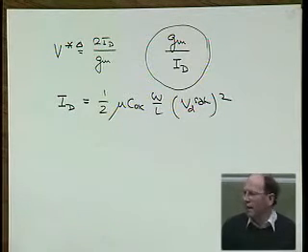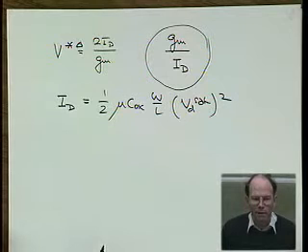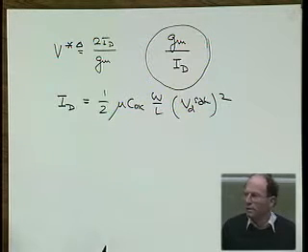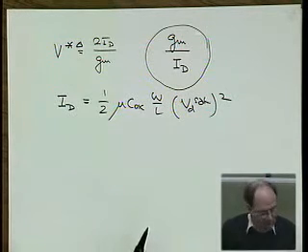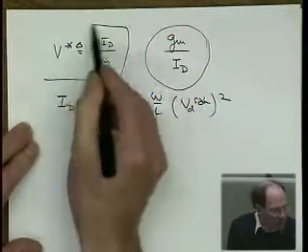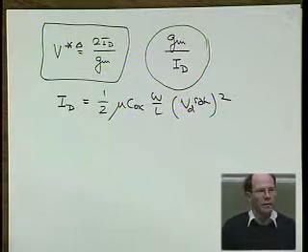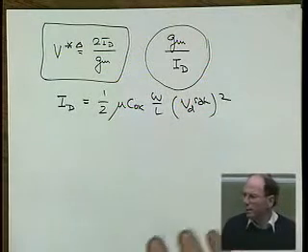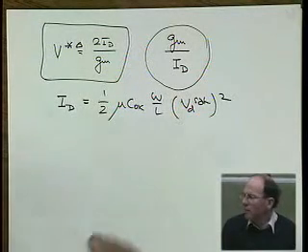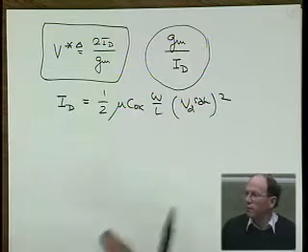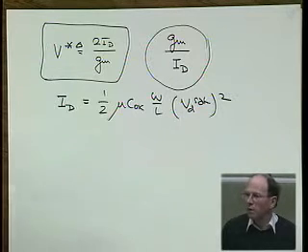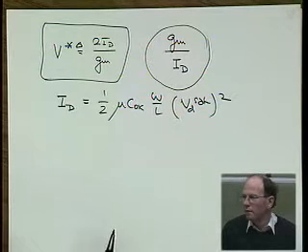It is sort of like an approximation of VDsat, but it's only an approximation of VDsat. Whereas this business here, this is the definition, is always accurate, totally independent. You'll never have this problem that, well, my calculations are going to be off from SPICE because fundamentally I make an error. Fundamentally, you do not make an error with this thing.